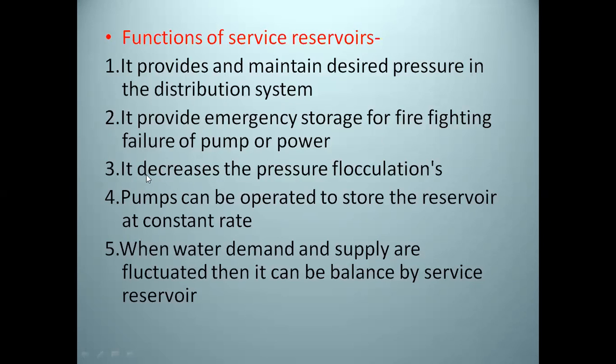Then the third function is it decreases the pressure fluctuations. It decreases the fluctuations in the pressure of water. Then pumps can be operated to store the reservoir at a constant rate. In the case we use pumping to store water into the service reservoir, then these pumps are operated at a constant rate.